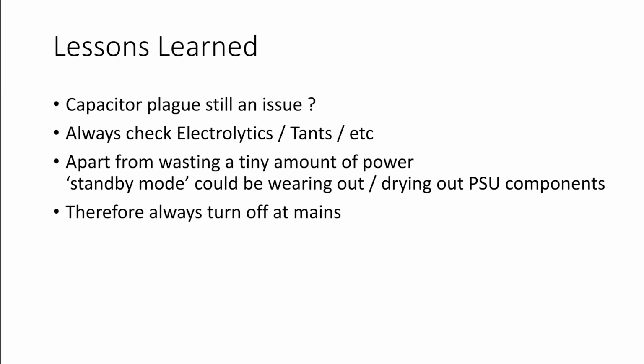There are some people that say it's cheaper and easier to just replace these with ones that you know are good than take a chance on them continuing. You've got the thing open, you've got the soldering iron warmed up, and it takes a minute of your life to do it. It's maybe just cheaper and easier to do preventive maintenance like that.